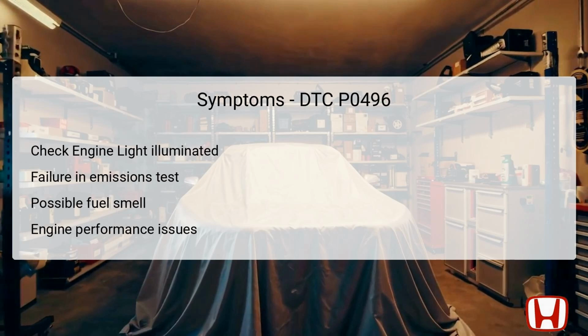Drivers might notice a fuel smell, particularly when getting out of the vehicle, indicating that fuel vapors are not being contained adequately. Furthermore, engine performance issues may arise, including rough idling or poor acceleration, as the engine struggles to manage the vapor that should be regulated by the EVAP system. Addressing these symptoms promptly is crucial for both performance and regulatory compliance.